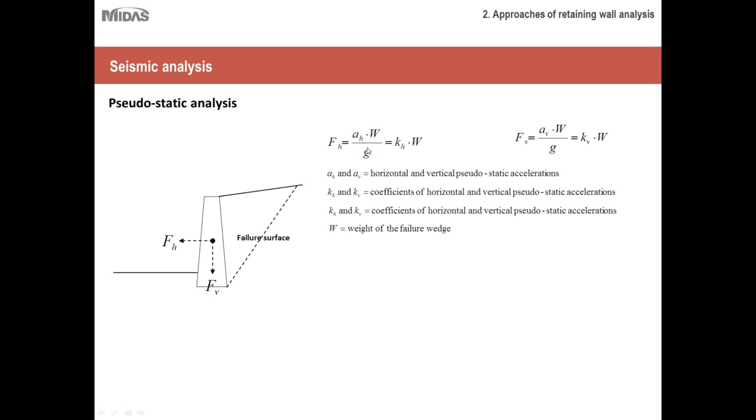It is actually the mass that you are considering that is acting onto the wall depending upon the angle of the face. So what we do is we first take the actual shape of the gravity wall, then we connect the dot at a given angle depending upon the internal angle of friction, and then we say that okay, this is the wedge that will fail.